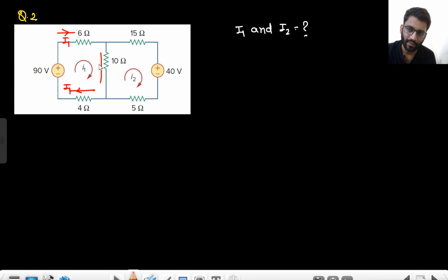In this branch we will have I1 minus I2, right? In this branch we will have I1 from the upside, I2 from the downward side. So I1 minus I2. Here we will have I2 current in this side, and I2 current in this side. Okay. So based on that, the polarities alternate plus and minus along the elements. This potential is already plus, this potential is also plus.